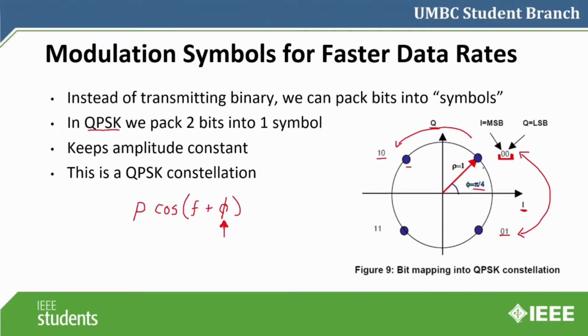And we'll get into what that means, but the benefit is that if you have an error and the received signal is this one, but you sent the 0, 0, that means you only have 1 bit position that gets messed up. If you made this one 1, 1, and you had that same error, you would get 2 bit position errors, which is the benefit of using gray code here.